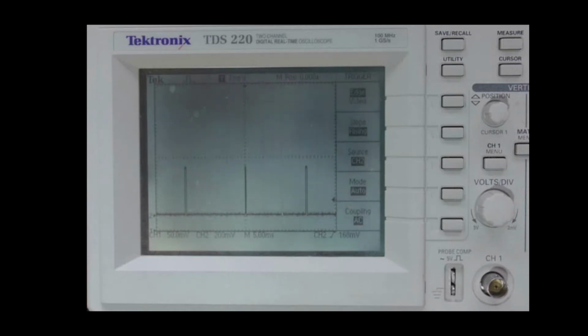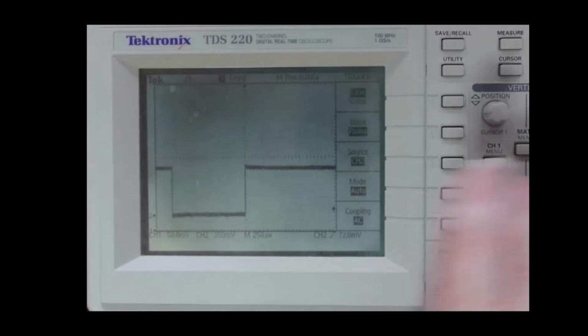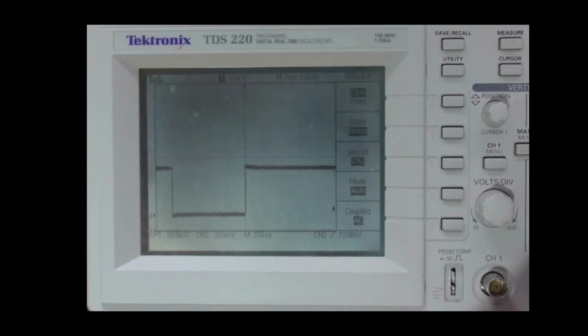This is the signal V5, which has a period of about 17 milliseconds, which is what we'd expect for a 60 frame per second update. And this is our vertical sync signal. The scope's having a hard time locking onto it for the same reason I think it had a hard time locking onto the horizontal sync. I think there are a bunch of short transients caused by the logic. It's only when I set the trigger voltage to be very low that the scope can lock onto it. It looks about a millisecond wide, which is what I'd expect for 16 scan lines at 64 microseconds each.